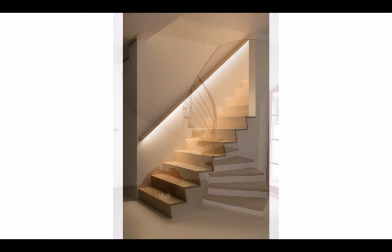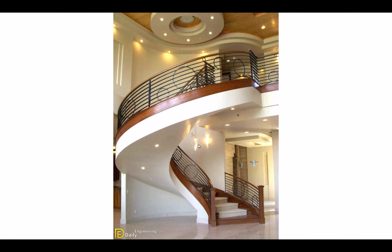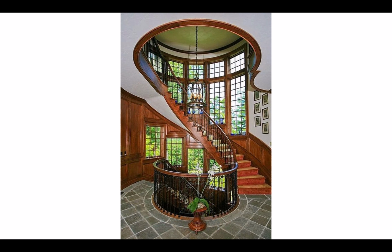So a number of varieties, and standard stairs, you know, Revit actually does a pretty good job, but as you get to more custom sorts of stairs, as the railings get more complicated, you see here these have like a funny circle motif, and then Revit starts to get really nervous. But Revit can do multi-story stairs as long as the floor-to-floor heights are the same. You can do a multi-story stair with just a few clicks as long as the first stair works.